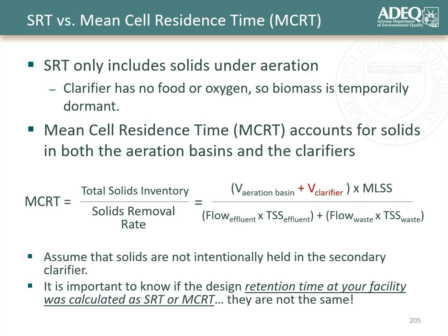And this assumes that there are no solids intentionally held in the secondary clarifier, which you could potentially have an increase in terms of the amount of solids in there compared to what you would expect from the mixed liquor suspended solids. But we're going to ignore that. This equation ignores this at this point. But what's really important is understanding what your system is designed for and making certain that you measure your performance based upon that design standard.